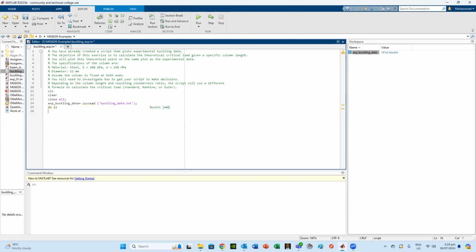And also it's given to us E, which stands for Young's modulus. Again, I write 200E3 because megapascal and millimeters work nicely with the conversion, so it will not impact me. And we can see that in SolidWorks as well. I will show you that when we start with the FEA analysis of SolidWorks. So that will come again here.